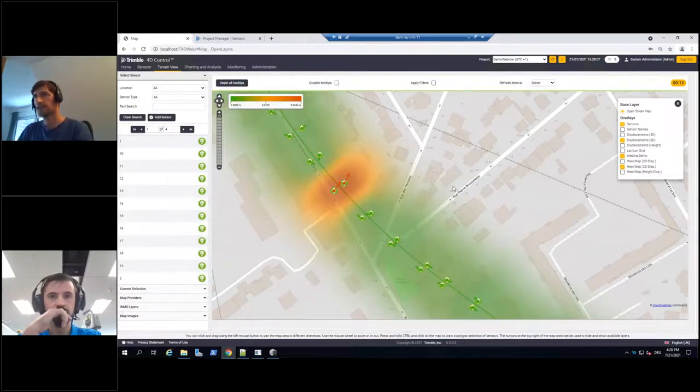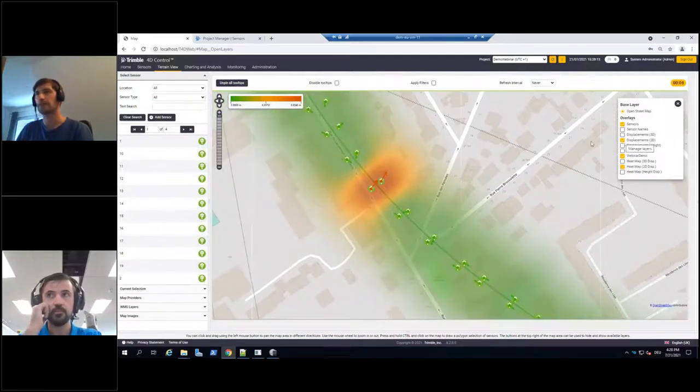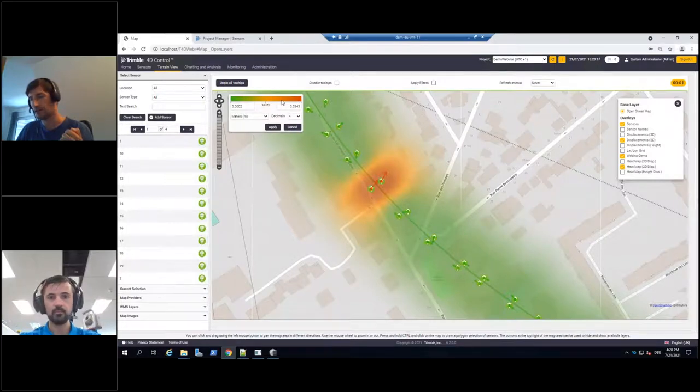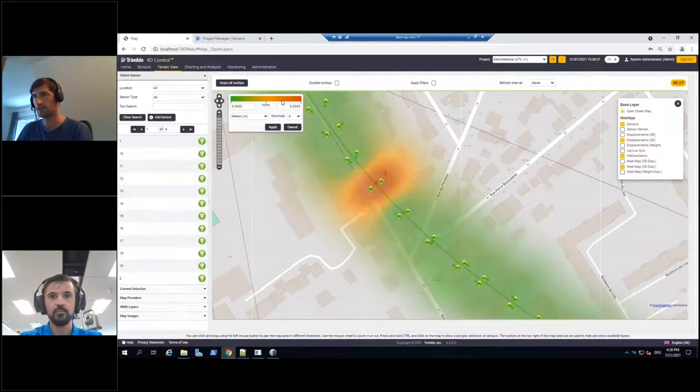I will come back to this later because I will also create an alarm definition. The vector size is something you can configure up here. By default, the scale is based on the largest displacement that came into the system so far. Anyhow, you can visualize everything: your alignment and your sensors. I guess this is what I wanted to show you.